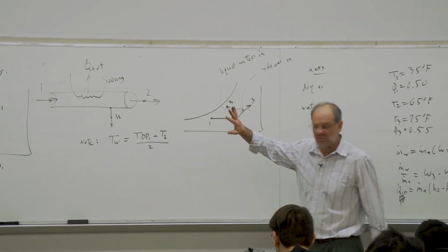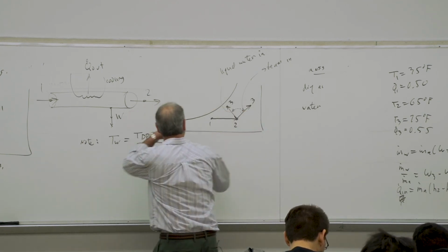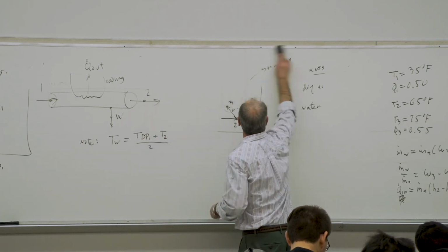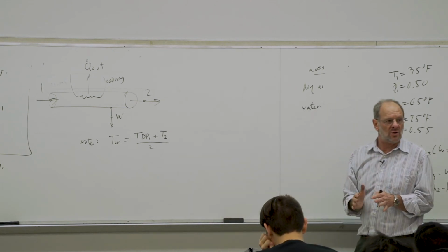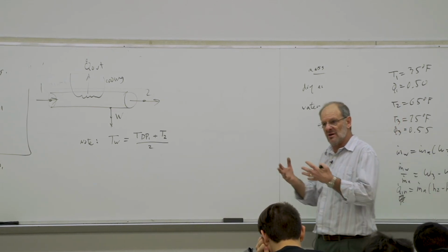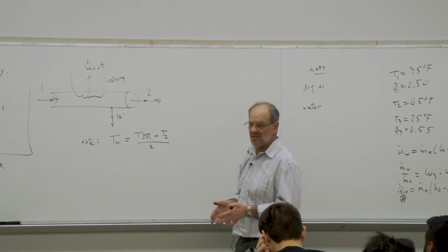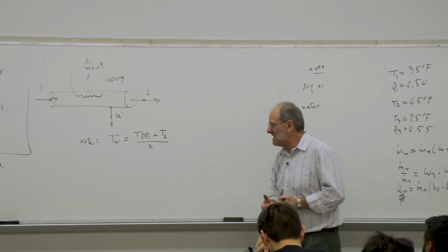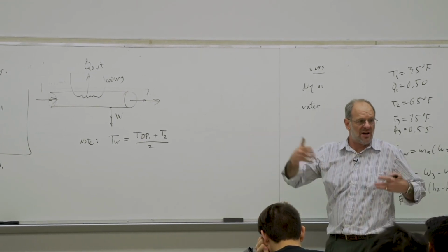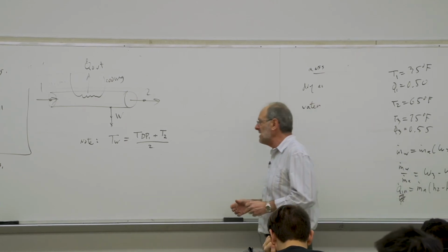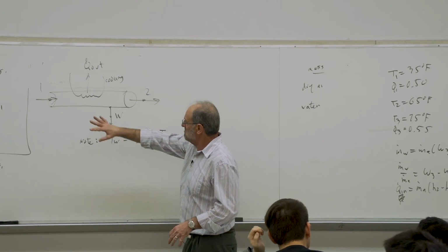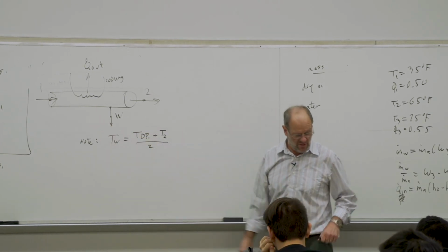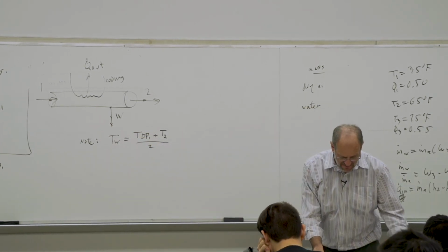When you look at problems of dehumidification by cooling in the textbook, what you're actually going to see is that the author will give you an assumed temperature of the water that's draining out of this air conditioning device. Okay? If that's what's given to you, well, yeah, go ahead and use that data that's been given, but personally, it's not particularly accurate. So I would generally find the temperature of the water using this particular equation.